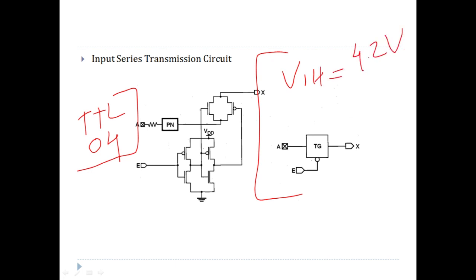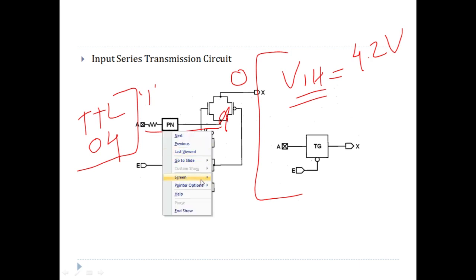In that case, TTL is actually generating a logic 1 output, but because it is less than VIH of the MOSFET circuit, it will assume it to be logic 0, right? Because there is no shifting of the level of an input in this kind of circuit.